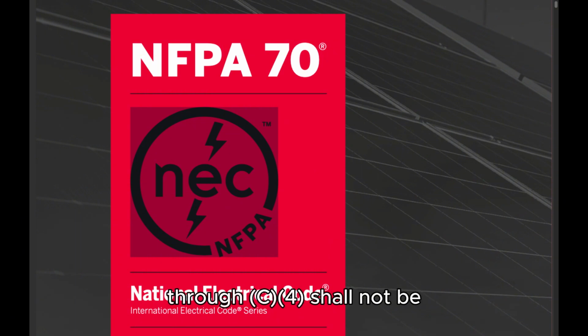The cases given in 90.9(C)(1) through (C)(4) shall not be required to use hard conversion, and shall be permitted to use soft conversion. 1. Trade sizes. Where the actual measured size of a product is not the same as the nominal size, trade size designators shall be used rather than dimensions. Trade practices shall be followed in all cases. 2. Extracted material. Where material is extracted from another standard, the context of the original material shall not be compromised or violated. Any editing of the extracted text shall be confined to making the style consistent with that of the NEC. 3. Industry practice. Where industry practice is to express units in inch-pound units, the inclusion of SI units shall not be required. 4. Safety. Where a negative impact on safety would result, soft conversion shall be used.